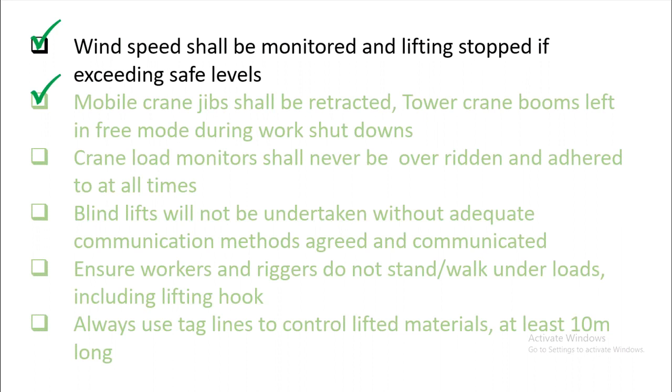For example, in the UAE, in Abu Dhabi, you need to stop all lifting operations if the wind speed is around 38 kilometers per hour. Or in Dubai, you need to stop if the wind speed reaches 39 kilometers per hour.